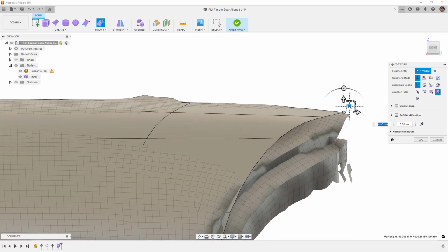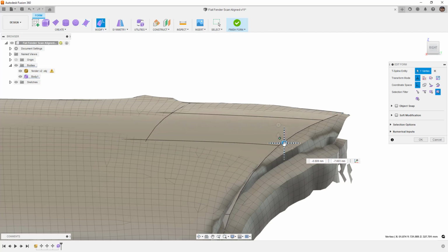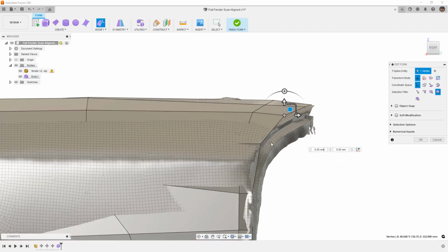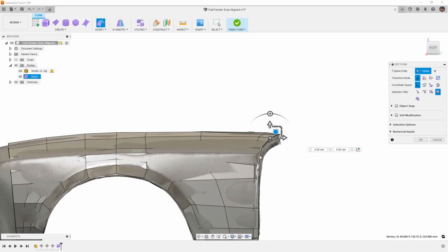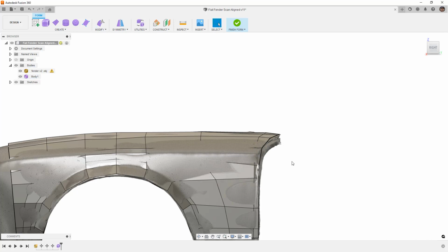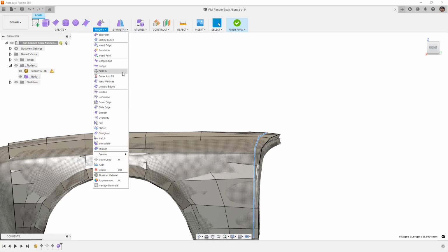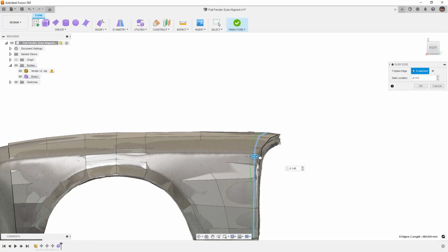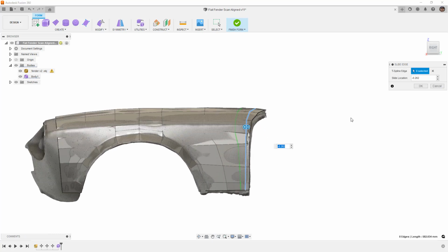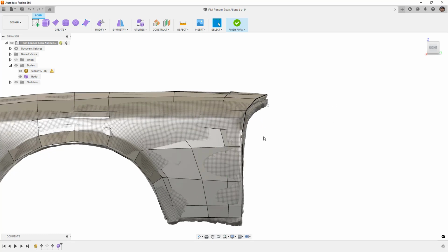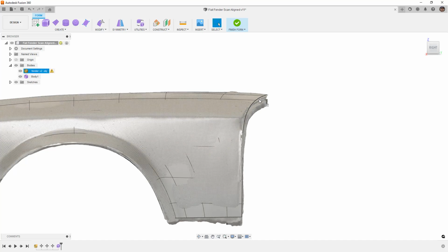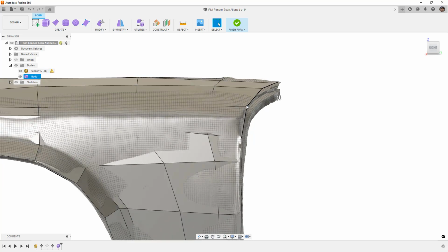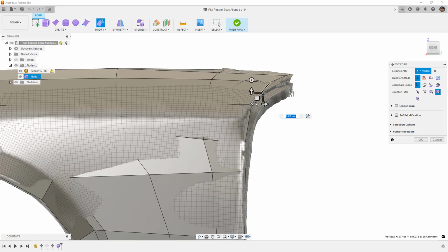And then I can start to take this one down until it goes into the mesh. I can take this one down. Again, generally, we're not working in smooth display. I'm going to go back and forth between box display and just play around with those. If you want to, we also can take this edge and use slide edge and pull it a little bit away, because we are generally looking for, again, a consistent distance between those patches. So moving that around is going to help us get a little bit closer. Once again, just going to manipulate this.